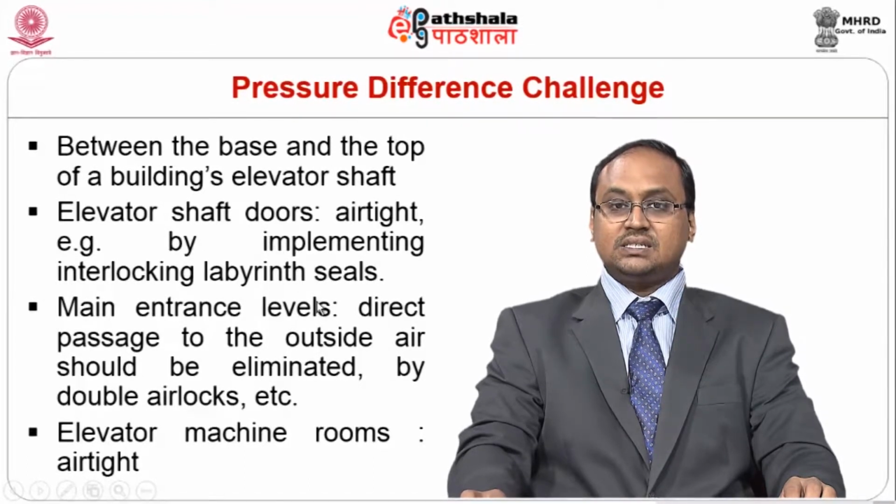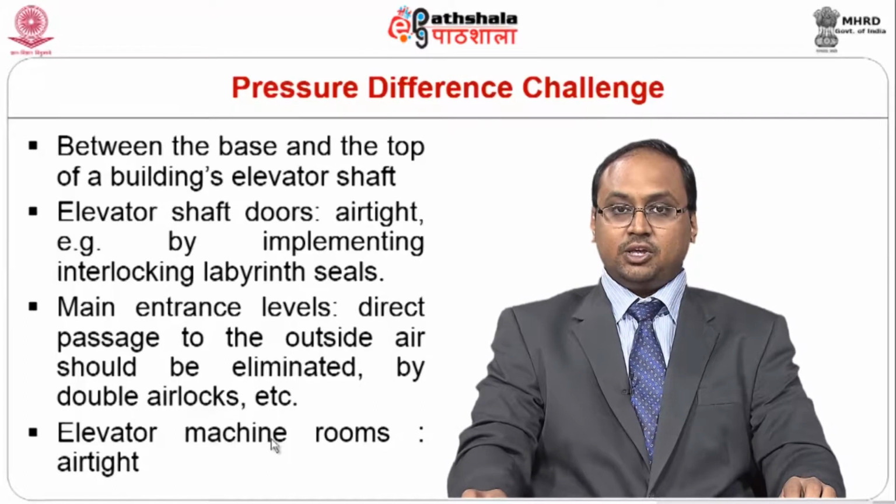At the main entrance level, we are aware that there is a direct passage to the outside air, and this should be eliminated by double airlocks. Elevator machine rooms at the top also have to be airtight, otherwise we may experience a huge problem because of pressure difference.